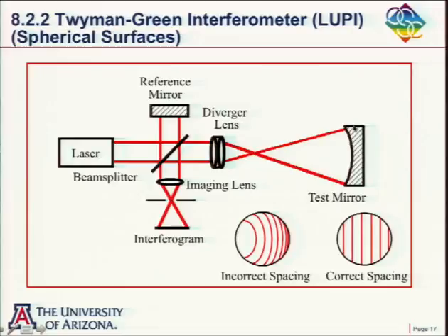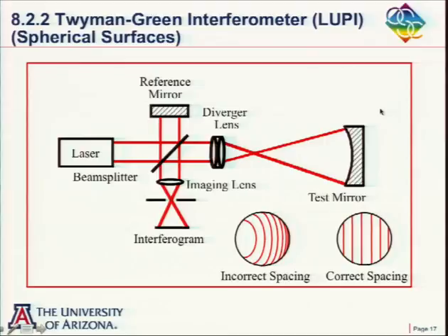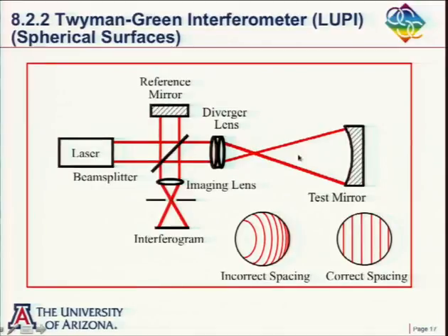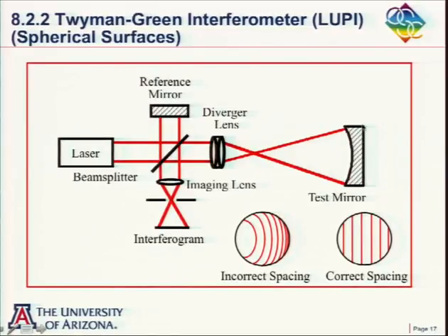But if I'm just looking at fringes here, the vibration really is bad. And there's a simple little thing you can do here that makes an enormous amount of difference. And you won't believe how much difference it makes unless you actually try it yourself. But say you have too much vibration here. If I just put something like a meter stick rest down here and back here, so I kind of couple the vibration.